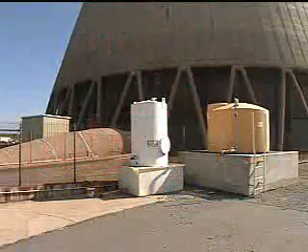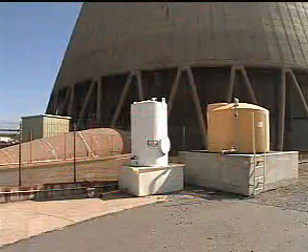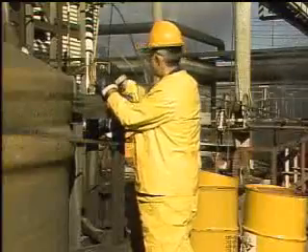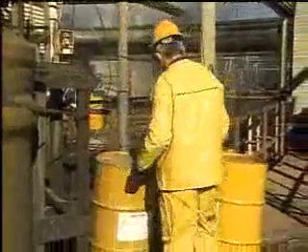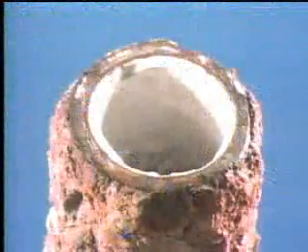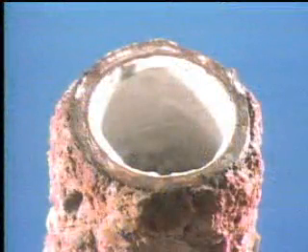The chemical injection system adds chemicals to the circulating water to retard the growth of contaminants, such as algae and bacteria. Other chemicals are sometimes added as well to reduce the buildup of hard scale in condenser tubes. If hard scale or other contaminants are allowed to build up, the heat transferability of the tubes will be reduced.